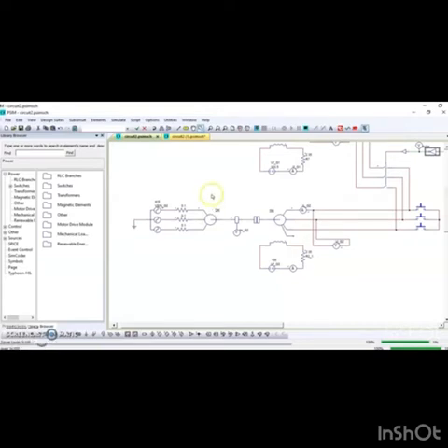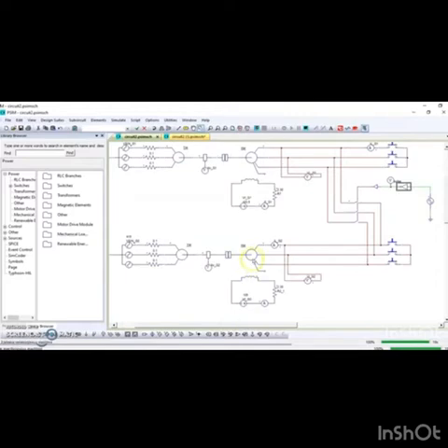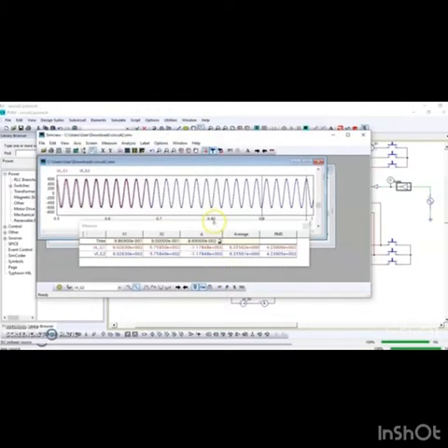Secondly, when it operates in the phase condition, generator 1 and generator 2 must have the same phase. Finally, at 0.1 second, both of the generators are connected in parallel operation, which produces in phase waveform.